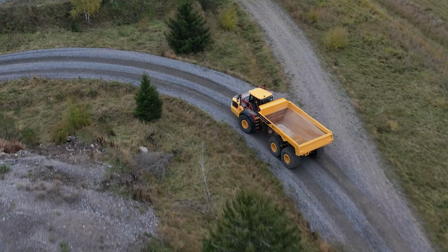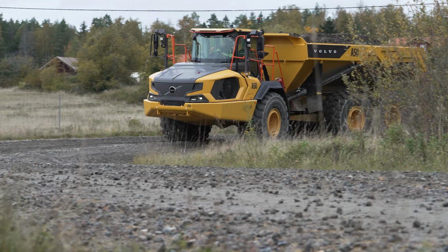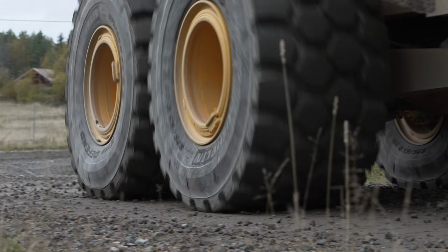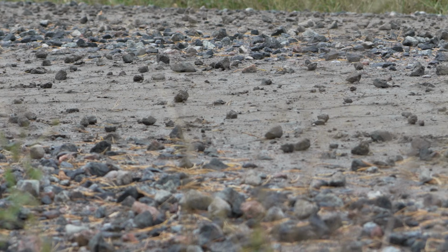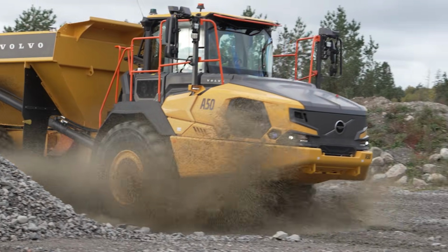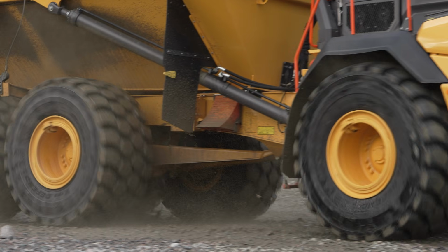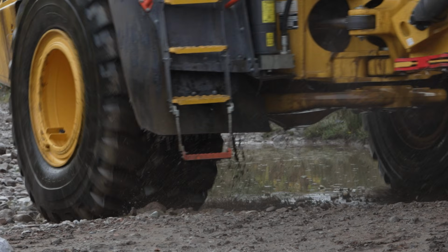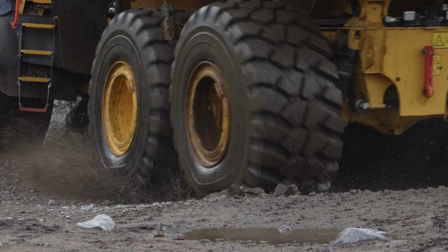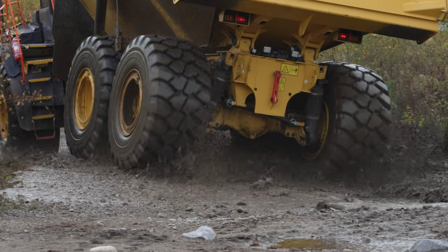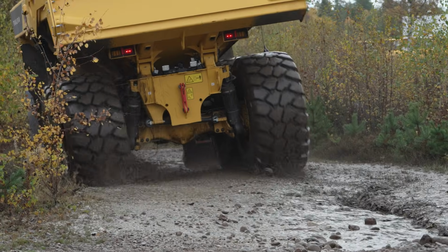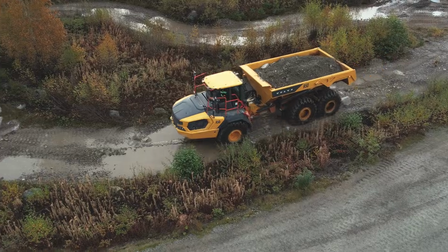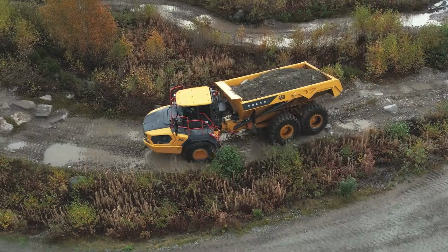The ATC switch controls the automatic and manual modes, which means that 4-wheel drive and 6-wheel drive are controlled automatically when the function is activated. The ATC automatically selects 6 or 4-wheel drive, depending on the ground conditions. The ATC also comes with a terrain memory, an automatic function that identifies and saves slippery surfaces using GPS locations. It will then automatically activate 6-wheel drive when you approach the slippery terrain during the next driving cycle.